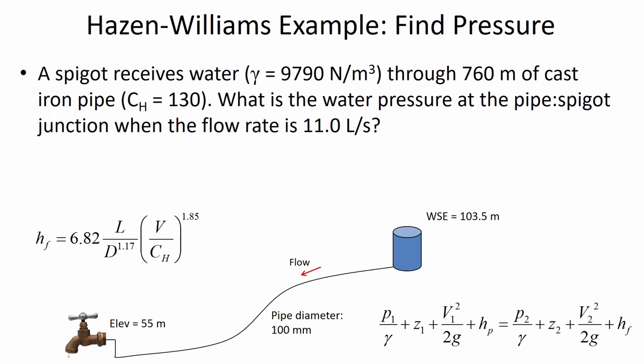But in the beginning, let's say here is the valve. All right. So the EGL is going to look like this. It's this dashed line. And we know the EGL should end, if there's water coming out, slightly above the water surface because it still has some velocity head. But I wanted to point out the fact that the EGL is coming along and then there's a sudden drop. And then it's above it again. This sudden drop is the energy that's lost as the water flows through the valve.